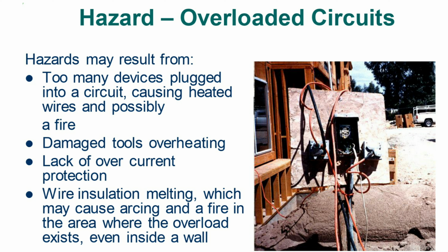Hazard: overloaded circuits. Hazards may result from too many devices plugged into a circuit, causing heated wires and possibly a fire, damaged tools overheating, lack of overcurrent protection, and wire insulation melting, which may cause arcing and a fire in the area where the overload exists, even inside a wall.